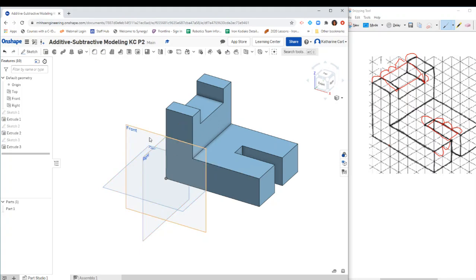If you don't want to see these planes anymore, remember, in your features list, go over to the planes and just click on the eyeball so that there isn't a line through it, and that just means that they are now hidden. It's really critical to always keep the origin in there. Origin really centers the whole drawing, okay? And that's it for now.